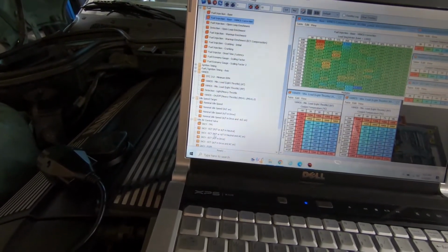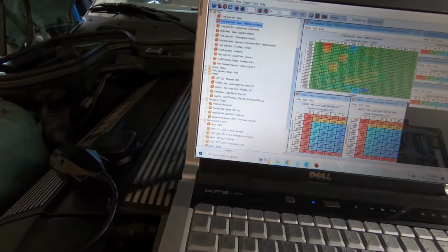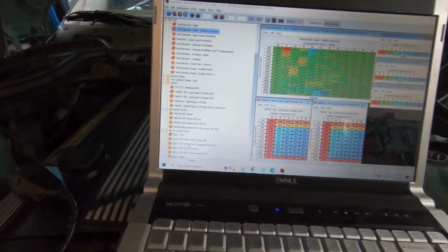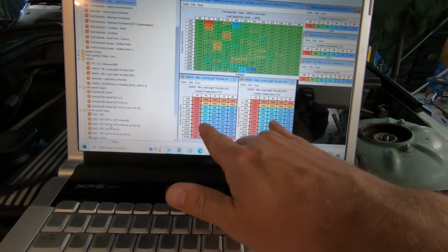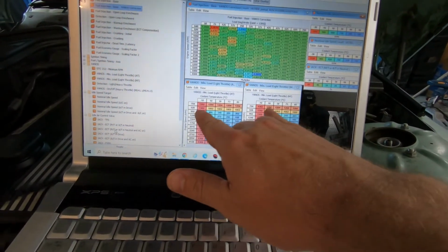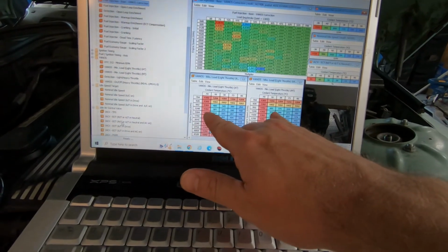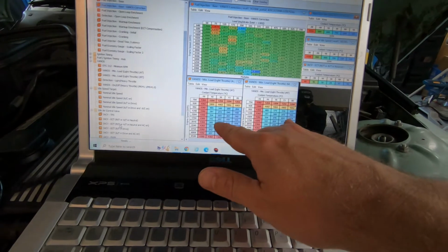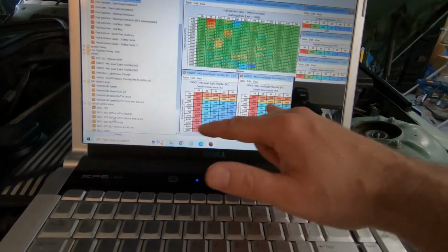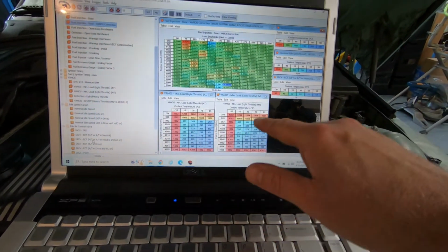And then the idle air control valve controlling. So the best I can see is between manual and automatic, there's an adjustment for the Vanos under light load for when it's engaged based on load, and it's slightly different between manual and automatic.